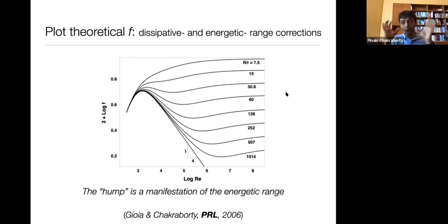In other words, all of the different salient features that we have talked about before in terms of Nikuradse's diagram, with this admittedly very simple model, we can understand, at least to first order, where these different features are coming from. And we can quantitatively predict the power law exponent of the smooth scaling, the Blasius scaling, and the rough scaling, which is the Strickler scaling.